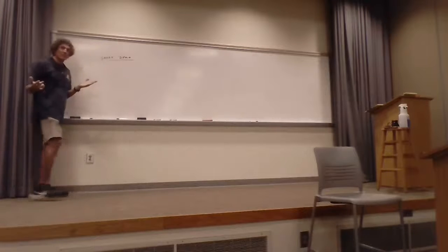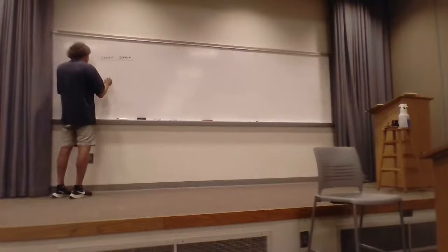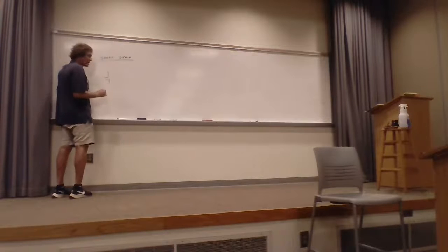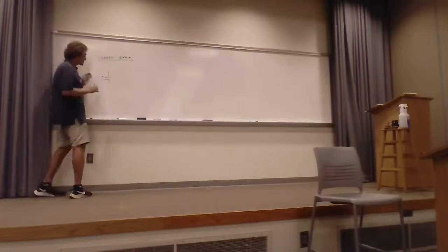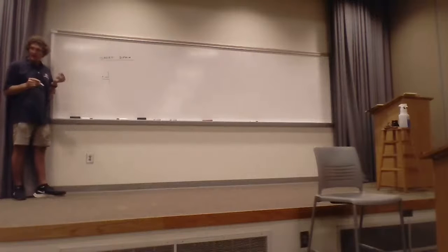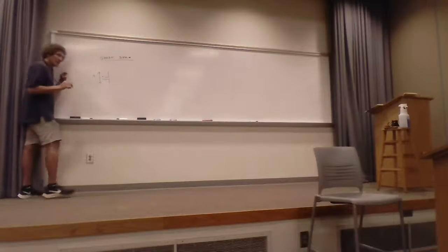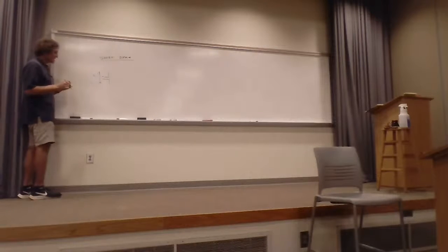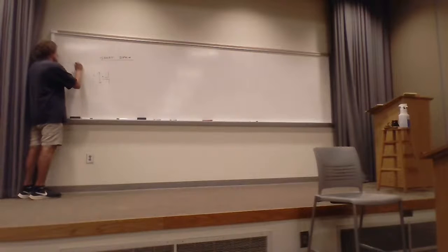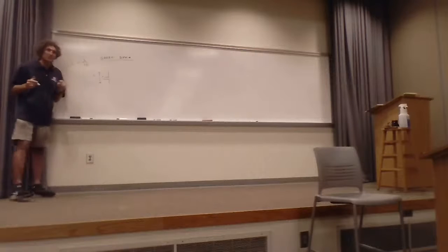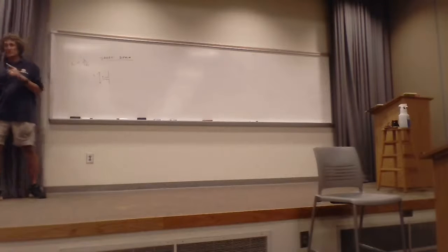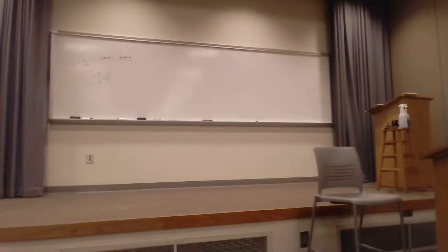Well, what is a short dipole? It's a piece of wire. Usually all these dipoles are center fed, which means the voltage is driving right at the center of the antenna. It's made of wire. It has a length L. All right. And that antenna has an L less than lambda over 10. That's our definition of a short dipole. It means if you know the wavelength, then that antenna better be less than a tenth of a wavelength in free space for a short dipole.